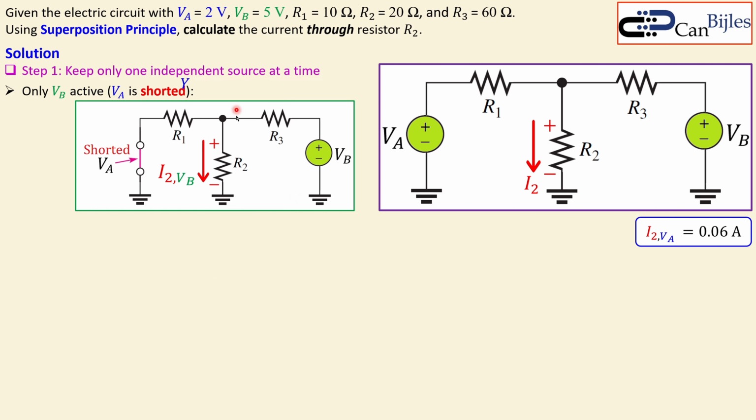And again, I will designate here another node that I also name differently. It is not the same node, also not the same resistance. So I will call this Y. Now I have another situation. So combine R1 and R2 now, and also make that series connection for R3 and the new resistor we will get. So if I now box this blue part, that will be the RY, which is the parallel combination of R1 and R2.